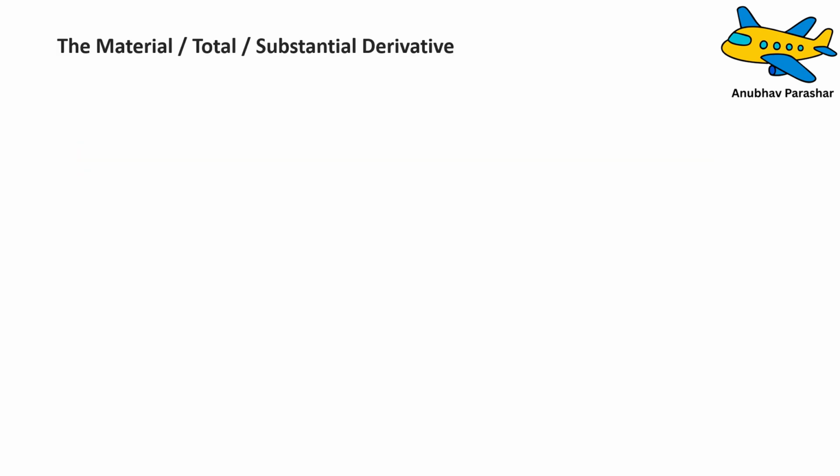Now here, the material derivative comes into the picture. It is the material derivative that helps us bridge the gap between Lagrangian and Eulerian. Basically, the material derivative transforms something written in the Lagrangian description into Eulerian. You'll ask how. This is what the derivative formula looks like: D by Dt is equal to, don't be scared, the partial derivative with respect to time plus velocity dot del into that property. Now you'll say, what kind of formula is this? It is completely going out of my mind. Don't worry, I'll explain it.